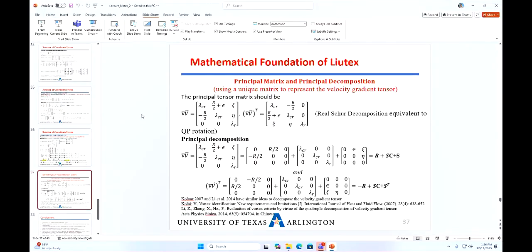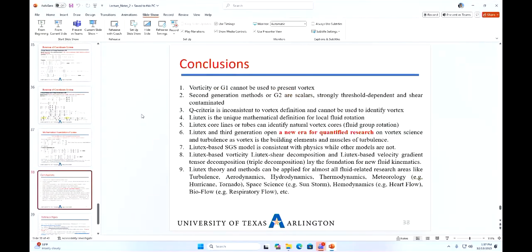You cannot rotate it or use other ways to transfer the stretching to be shear. This part is not transferable. In general, the diagonal element can be rotated to become shear, but not for this. Be careful with this when we talk about turbulent flow. Turbulent is different from laminar flow. A lot of theories will disappear. Be careful with that.